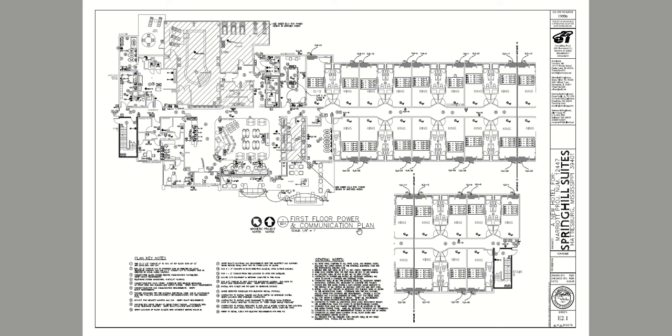So with that in mind, remember our pad mount transformer was up here, and the reason for that is because our main electrical room is here. And so we usually want to try to put that pad mount as close as possible to the main electrical room. The reason for that is that secondary run, our contractor / owner is responsible for that. So the shorter the run, the less money we have to spend to do that. So we usually try to locate it as close as possible.